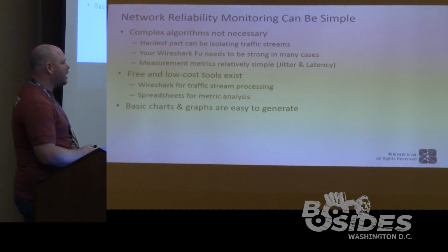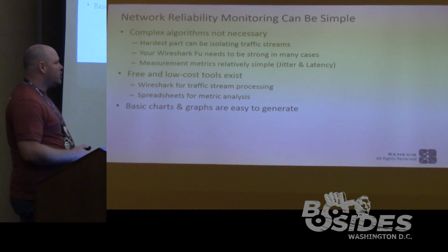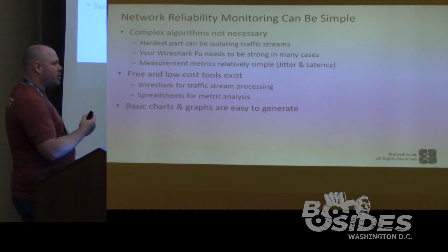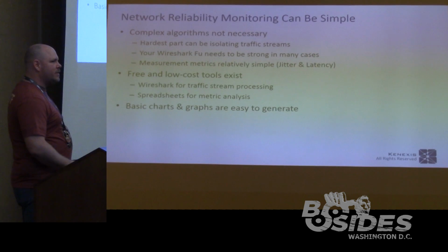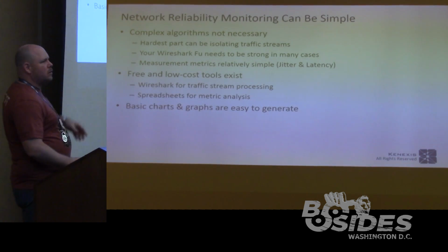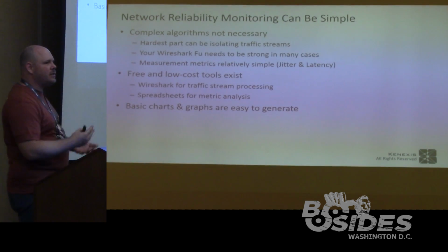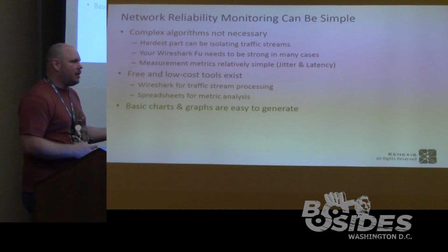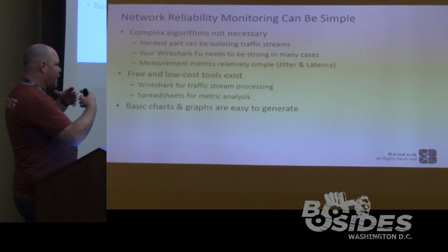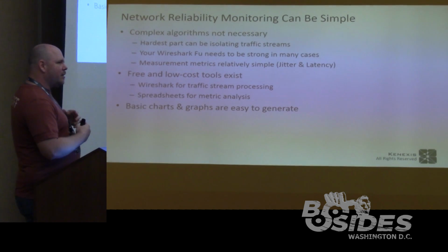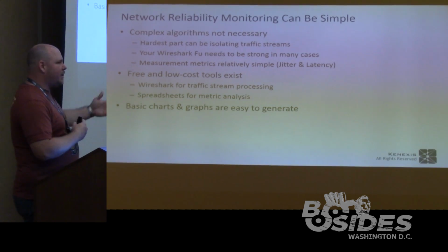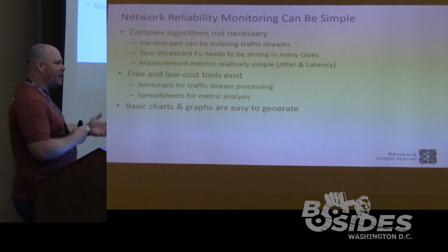And the metrics you're looking at aren't very difficult either. So you're looking at jitter on a deterministic signal. You should be getting a straight line across there, and all of a sudden I have some wiggle in there. Why? And so you go investigate that. And then latency. With these systems, as a controller, I talk to some device, and that device responds back. What's the latency there?